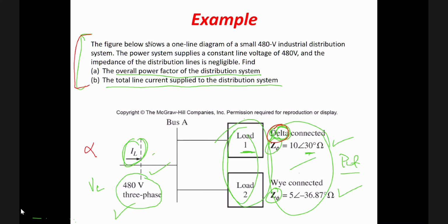But usually I specify: I say that the phase voltage in the Y connected source is 120, or the line voltage is 120. Or I give it to you like the first example, if you remember, like this, 120 angle 0, so it's clear that this is the phase and this is the line. But if I don't give you any of these indications, just consider it as phase.